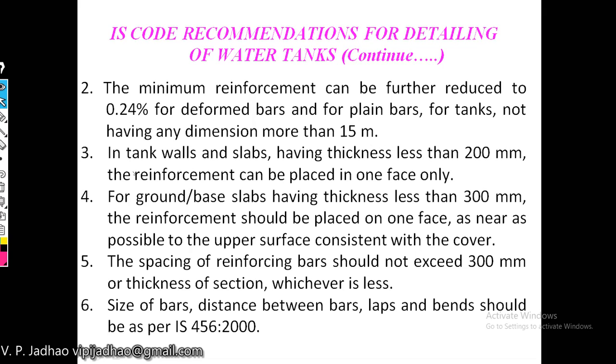The third recommendation is that in tank walls and slabs having thickness less than 200 mm, the reinforcement can be placed on one face only, if we have depth like this. If the depth of the water tank slab is less than 200 mm, then we can provide it at one face, that is at the top.